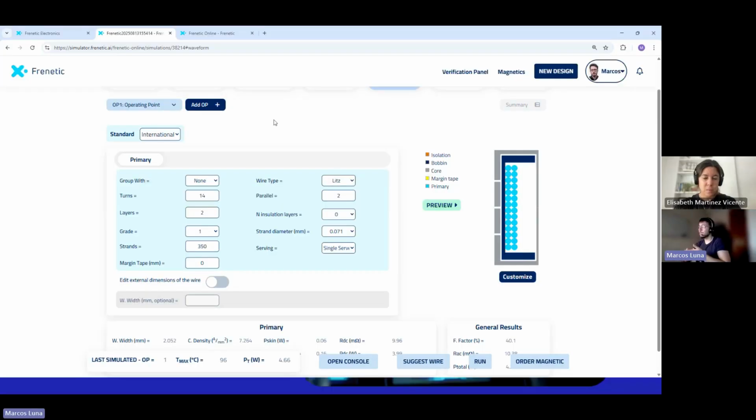And the second one, maybe I don't understand: can you simulate bifilar winding done in 2 layers and 2 single filar windings connected in parallel? So let me show you the possibilities that we have here. At least from the winding perspective, we are in an inductor. With a transformer, there are more combinations, and you can also combine or twist, for example, secondaries. And here, apart from simulating the leads wire, you can simulate also round wire, foil and rectangular wire.